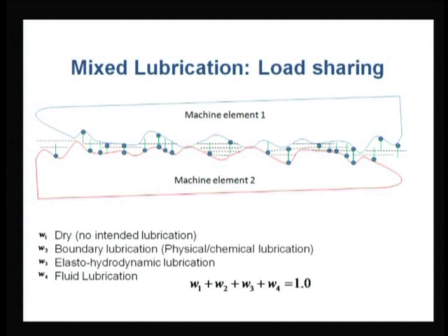If we are using a thick lubricant and operating at a higher speed, the friction will be on the higher side. That was also indicated by the Stribeck curve. If the sliding velocity is higher, in a fluid film or hydrodynamic lubrication mechanism, the coefficient of friction will be on a higher side.